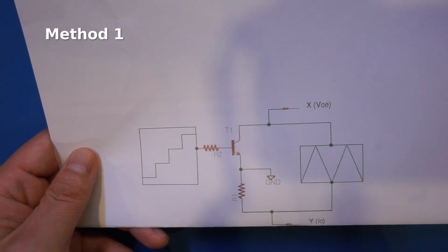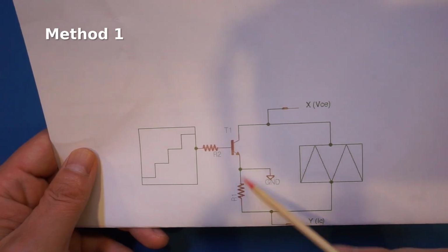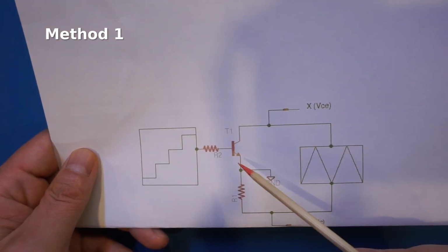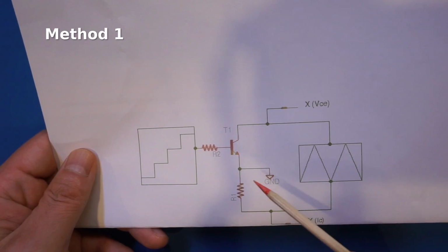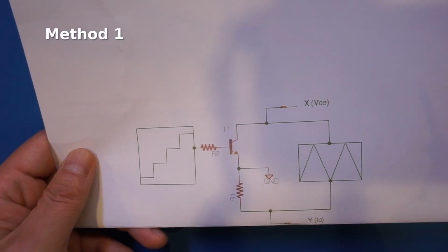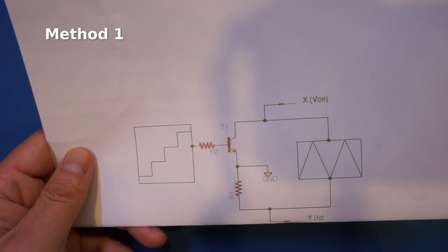the transistor here. As you also notice, technically speaking, we're actually measuring the IE, not IC. But since the gain of a transistor is fairly large, the current difference between the IE and IC is pretty minute, so most of the time this difference can be ignored.